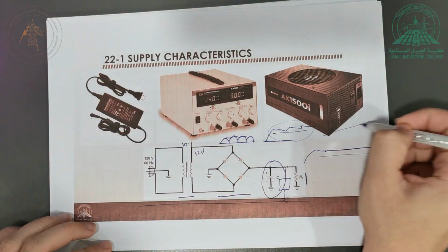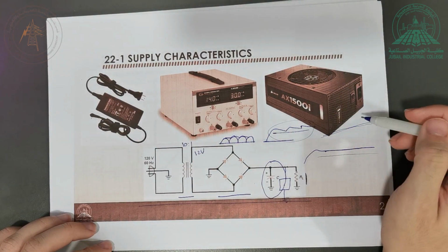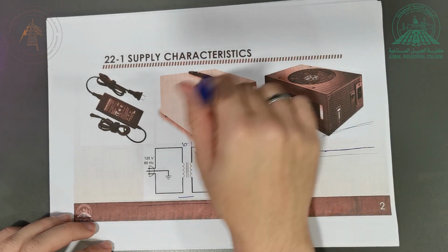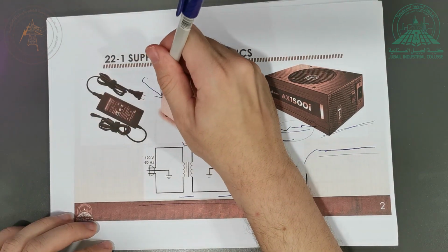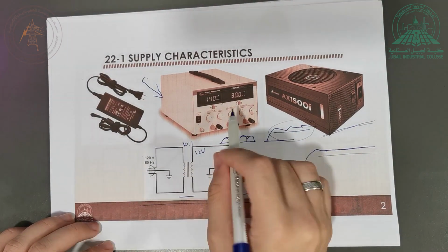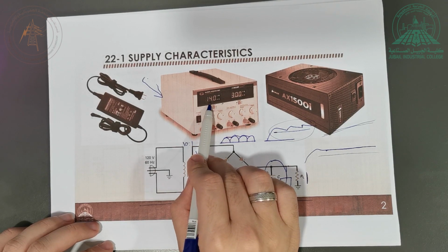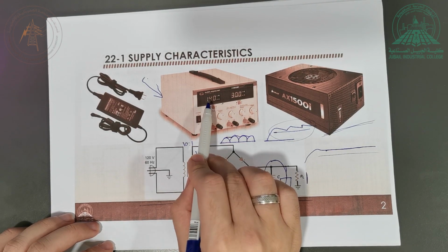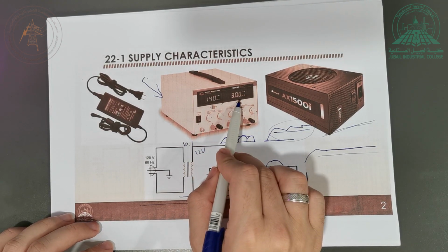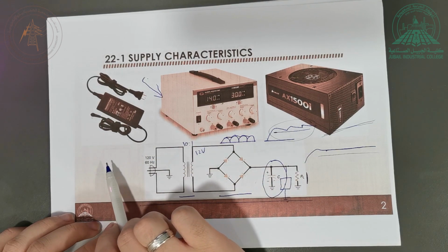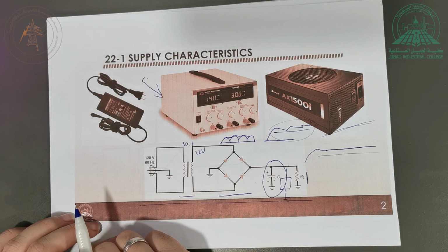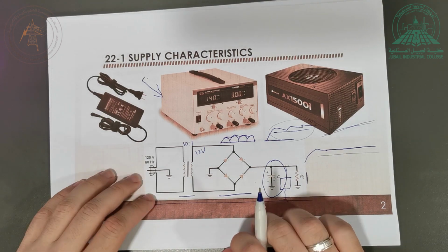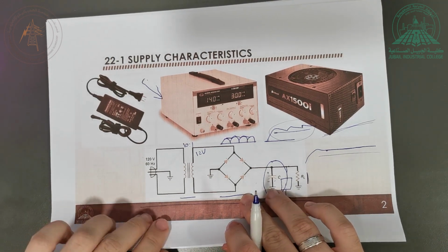Here you have the power supply inside your PC. If you have a PC, this is the power supply. It does almost the same job. And this is the power supply that you have seen in the circuits and the electronic courses. So again, you supply the electrical AC input from behind here, and then you can control whatever voltage you want here. You can set the voltage. You can also set the current limit, and you can give this constant DC voltage to your device. So this is basically what we mean by a power supply.